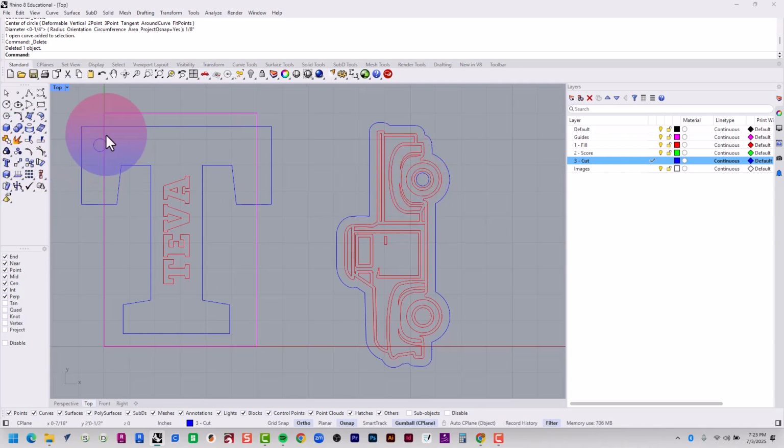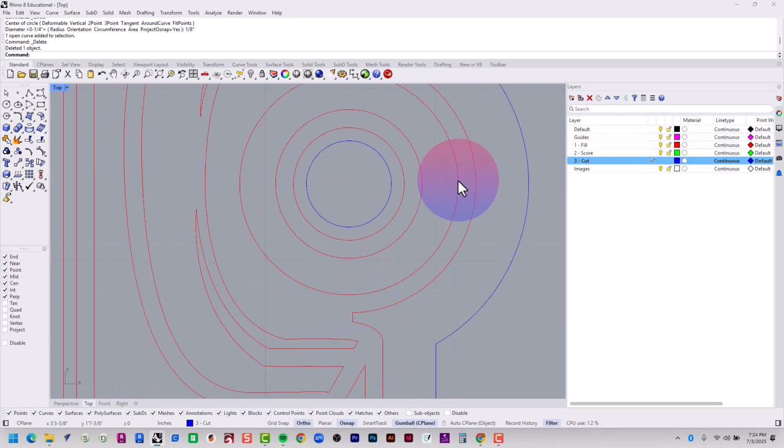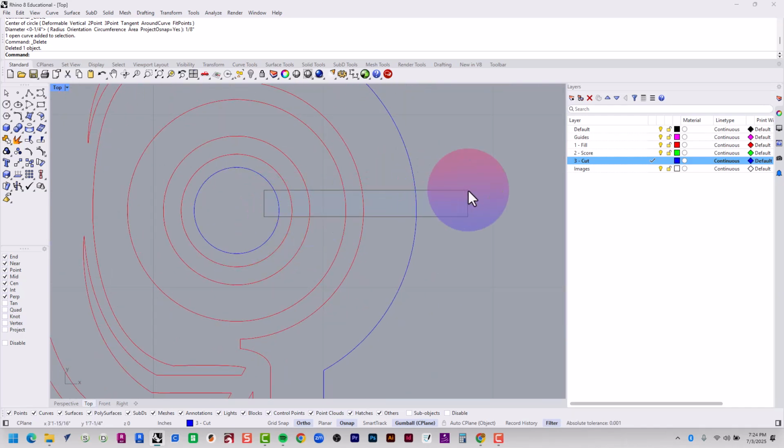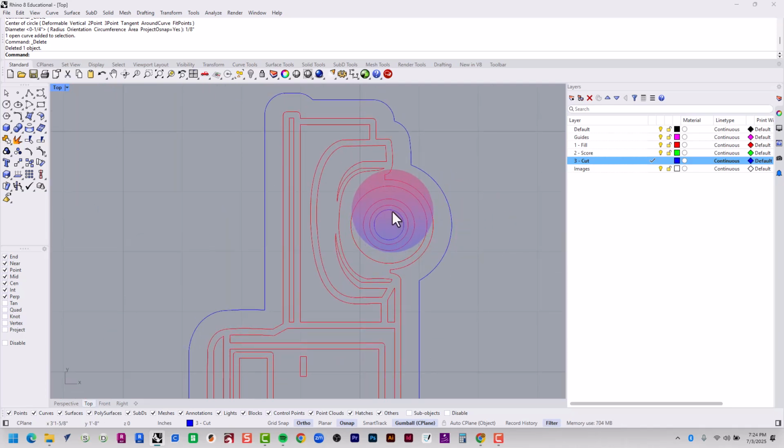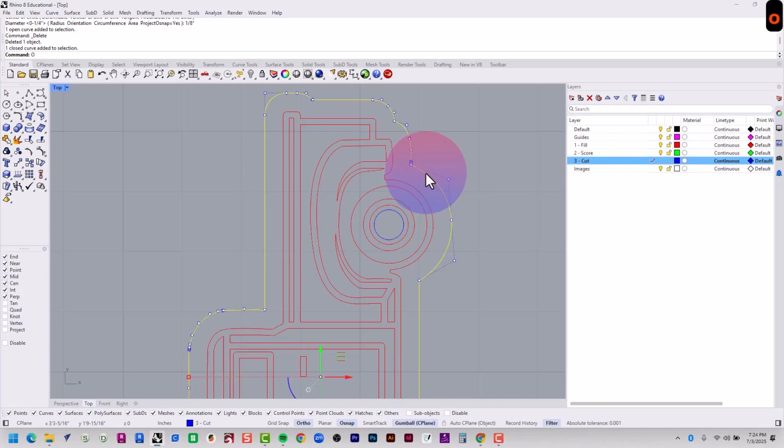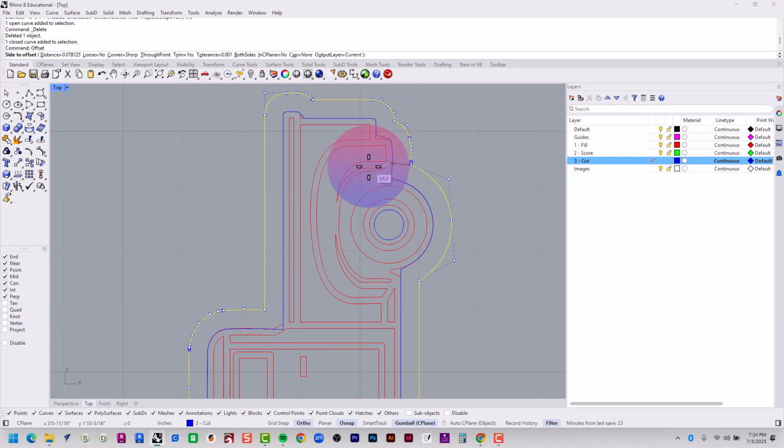So there's my 1/8 inch circle. It's going to be right there, and it's going to hold my key. Actually, this is going to be way too far away from the key ring, and it's going to make it really hard to put this thing on. So that can't be the spot it goes. It's going to have to go about 2 to 3 millimeters away from the edge. So if I offset this line inwards, let's try 3 millimeters.